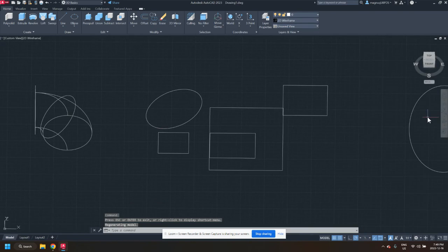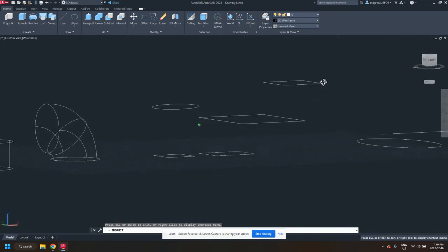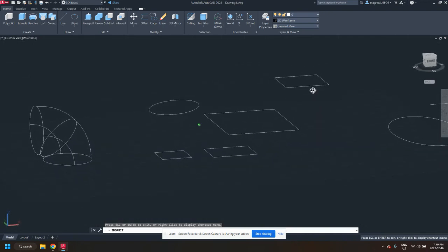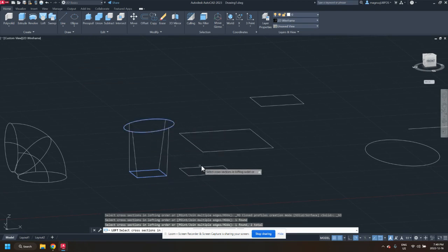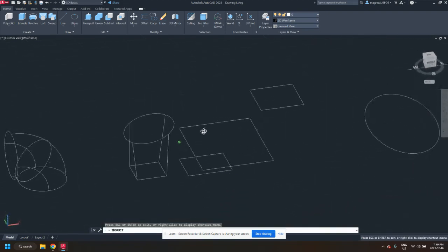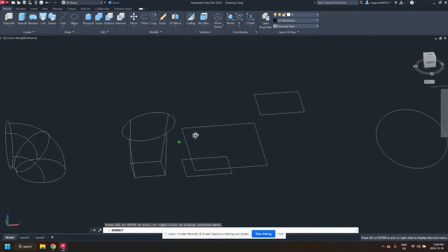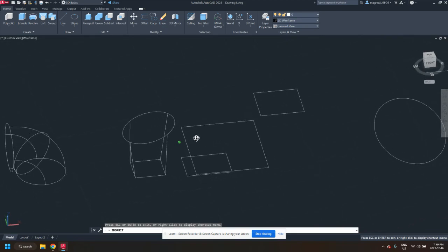The next feature that we can go over is the loft feature. This feature essentially just connects different layers. To have it work, you need to have a bunch of objects at different elevations or on different planes. We're just going to say Loft, and then you select them in order. So we'll go from this to this, and that will create a nice route up to meet with that. You can see it goes like that, and all the corners line up with the circle. It doesn't work the best with circles and squares; it's a bit of a bad example, but I have another one here.